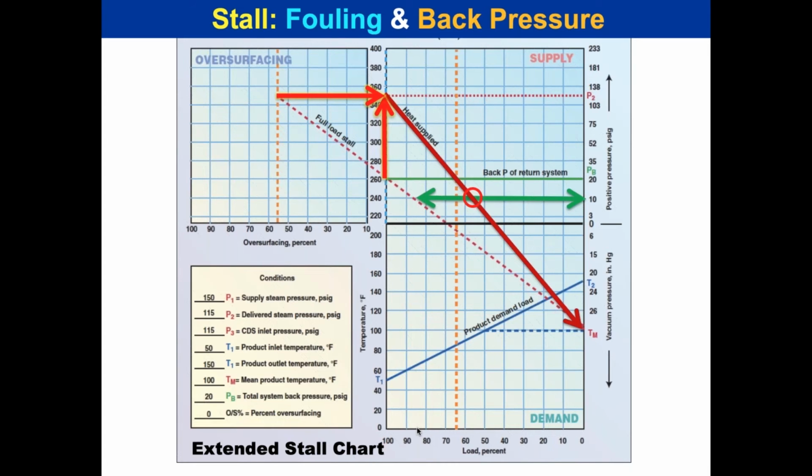But now here's what happens, and it's very confounding for people on site, and I want you to think about this. They don't have budget money, they have gap years, they wish they could fix the steam traps, they just don't. They didn't pay attention to the open bypass valves, they didn't pay attention to the blowing traps, whatever. And what happens is the back pressure goes from 10 to 20. You see it jump up there to 20? It happens gradually. It could just be 1 or 2 heaters opening up bypass lines if they're large heaters with 2-inch lines.